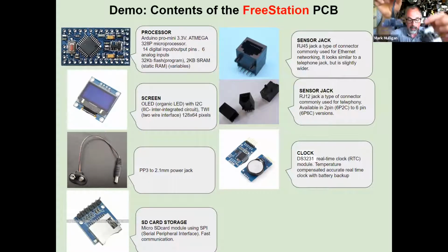This has a cable attached to it. We use standard cables for everything. This is an Ethernet cable for a computer. And then at the other end, there is a sensor. This is a sensor of temperature, humidity, and air pressure, called a BME 280. And as you see, it's just connected to the other end there. And so you can build that in an hour for about £30. And there you've got a data logger that will, every few minutes, wake up, take readings of temperature, humidity, air pressure, go back to sleep, and then write them every hour as averages. And you can then look at that data.